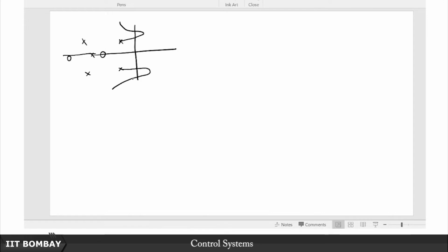Now imagine that you have chosen a particular value of k such that your closed loop pole is here, right. Now it might be that you reduce this gain in the hope of improving stability, but on the contrary what this will do is take your closed loop pole closer to the j omega axis. So there could arise a situation where reducing the gain is detrimental to stability.